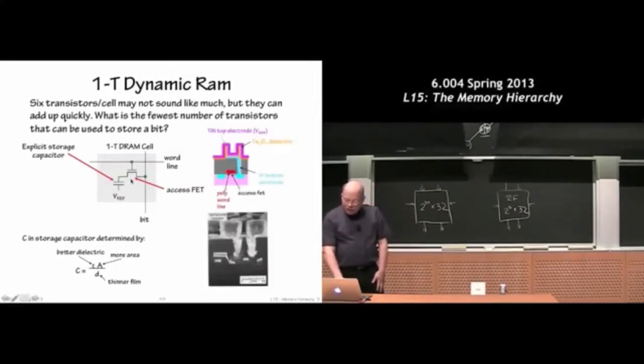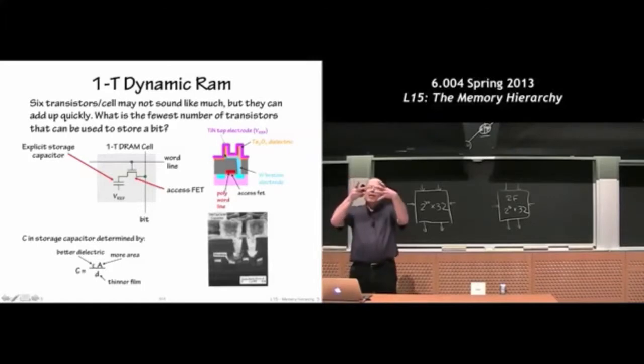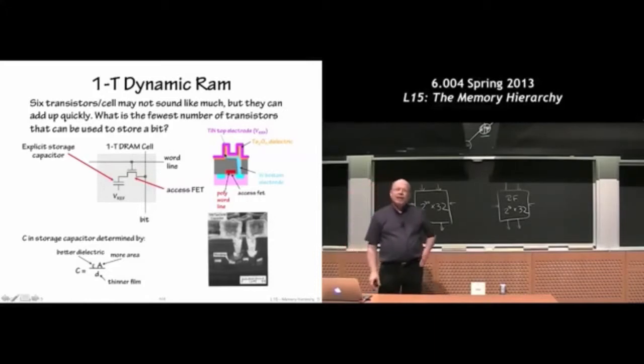And so you start getting very strange looking structures. I don't know how well you can see this in the slide. This sort of looks like a rotten tooth, right? What it really is, is a cylinder where there's an internal metal cylinder that's been covered by a dielectric insulator, and then there's another metal plate that's gone on top of that. So I've made this cute little metal-dielectric-metal sandwich, which is basically a very small capacitor.